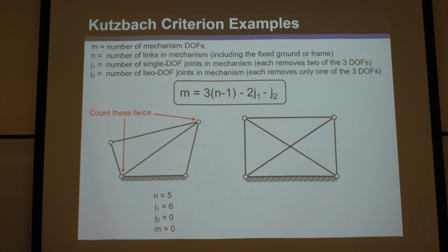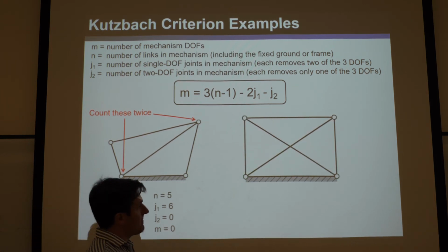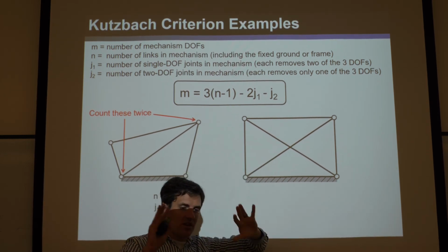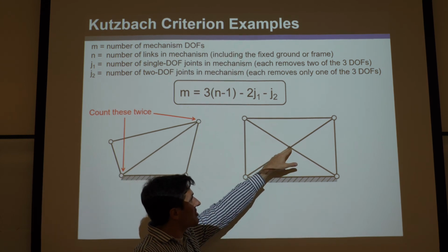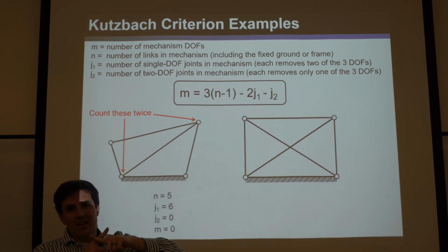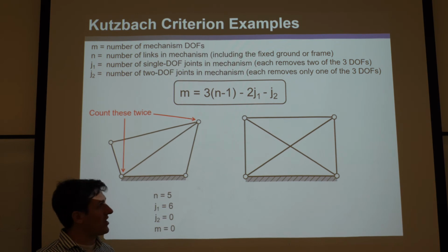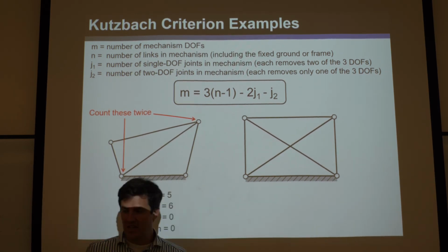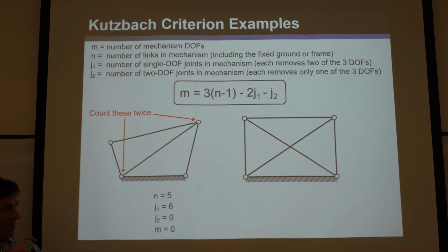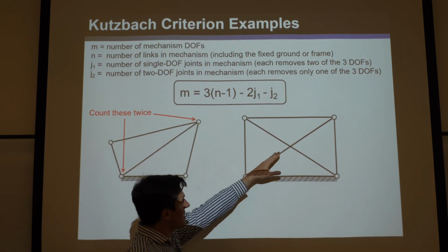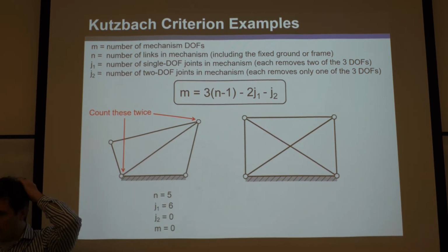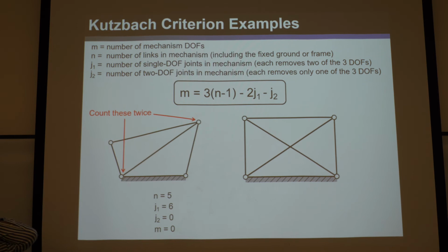Okay, let's look at this system here. You see these bars are kind of crossing. Just pretend these don't even touch. They don't interact. It's not a joint there. If you just see 2 lines overlapping, you do not assume it's a joint. You can assume they don't touch. You can imagine this goes underneath and this goes over on top. They don't need to draw anything like the circuit diagram circle over it. The joints will always be drawn as prismatic or revolute joints, or however I taught you in the skeleton diagram.